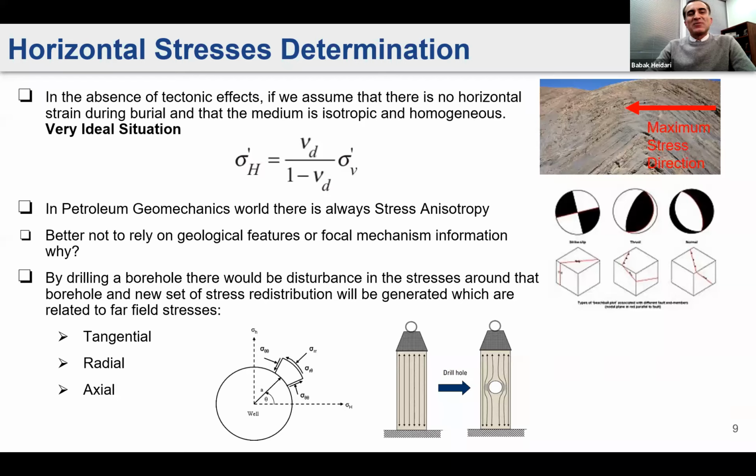And there is a relation as defined, for example, by Kirsch, the simplistic approach for the isotropic, hydrostatic, and homogeneous formation developed by Kirsch. And there are more sophisticated approaches, for example, what I am using right now, finite element codes, but they are basically saying the same thing, that there is a relation between borehole information and the far field.